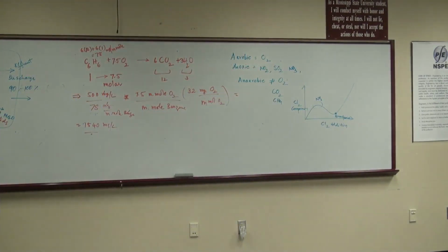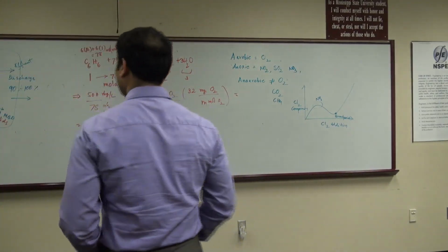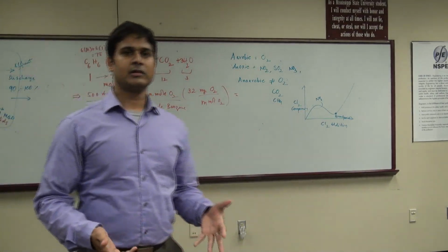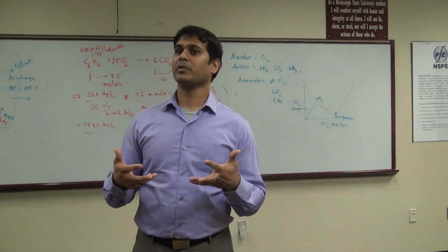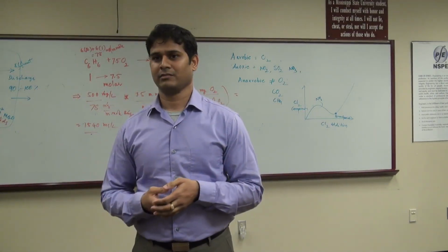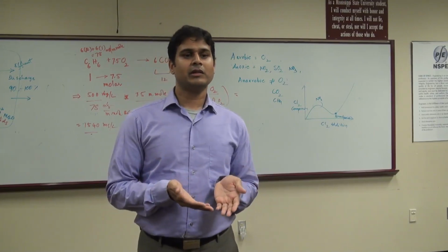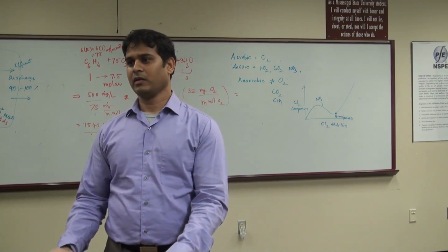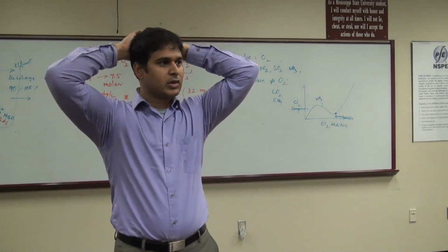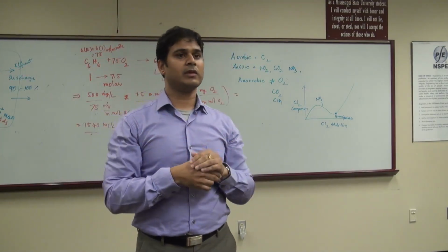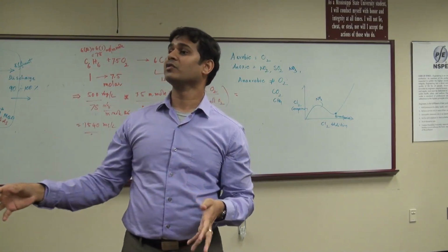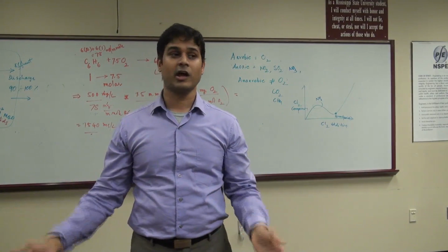That's fecal coliform. If you see the units for fecal coliform, they start with 10 to the power 6 per 100 milliliters. Your BOD is just how much? 200 milligrams per liter. It's low. Your fecal coliform is so high. But once you treat the wastewater, at the end they almost go to zero. So which is the highest reduction?